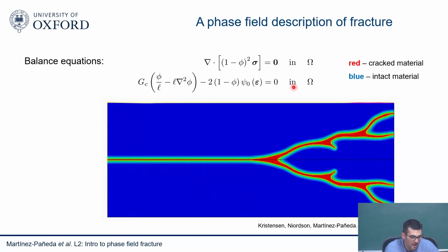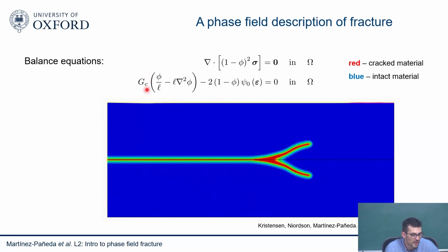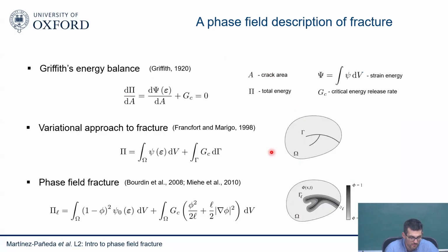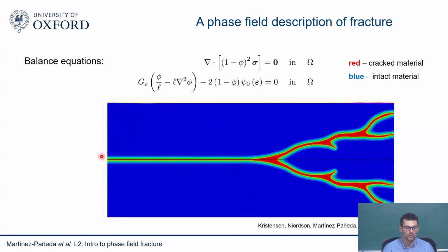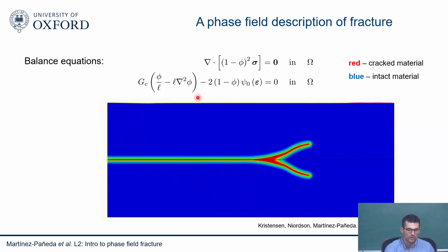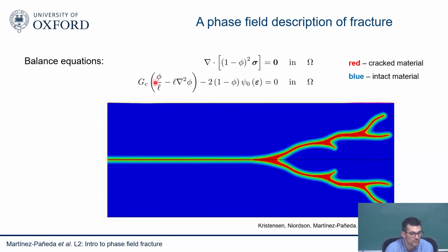And you effectively see that what you have is a competition between the toughness, a material property that we can measure, which is the connection between the damage and the fracture, and the strain energy density. Everything relies on toughness and the strain energy density. And by the way, mathematicians have shown, through gamma convergence, that this regularized functional converges to the Griffith functional. So we'll do some numerical tests to confirm that this is the case, but in principle, mathematicians have shown rigorously that by solving this equation, you are going to predict that cracks grow based on Griffith's energy balance. When the critical energy is reached, when your stored energy equals your fracture energy, cracks will grow. And just by solving this differential equation, the quantity you are solving for is, of course, the phase field.